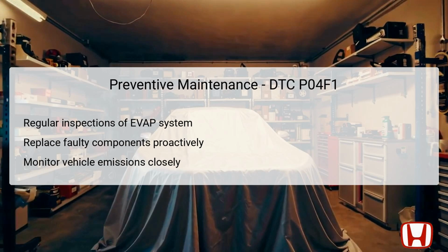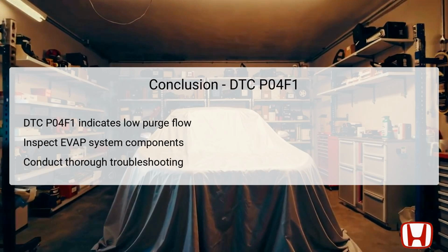By committing to these preventive measures, vehicle owners can enjoy better performance, fuel economy, and lower emissions, maintaining the Honda Fit in optimal condition. In conclusion, DTC P04F1 signifies a low purge flow in the EVAP system, requiring thorough inspection and troubleshooting of all associated components.